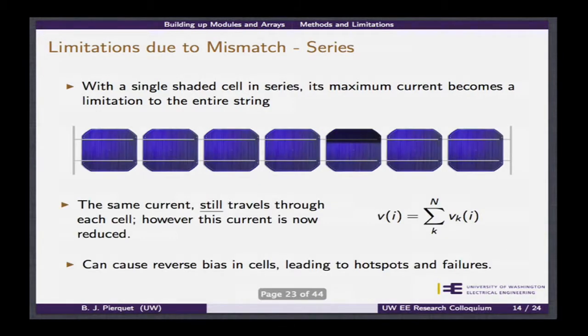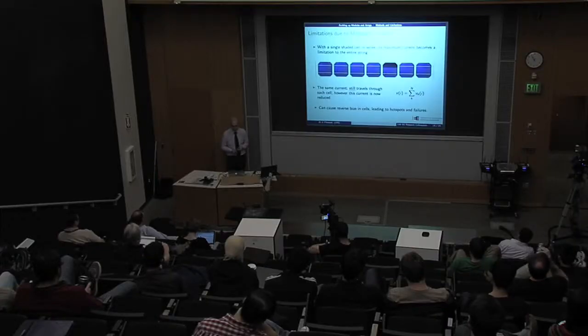The same applies to here. You could put a diode across this. So if the voltage across here becomes reverse biased, you have a diode that just bypasses it and it's done. But usually we're not willing to put a diode across every single cell. You have 60 diodes across every cell, and each diode has to handle the current through that string. And so it becomes a relatively expensive and not necessarily more reliable viewpoint, because the expense is high. You use very inexpensive diodes, which are prone to failure.